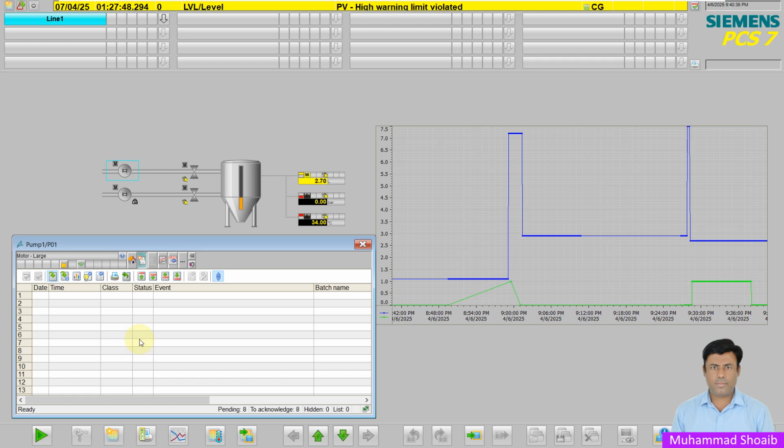The motor protection block already has some default alarms configured. That name is motor protection. It's already configured by default. But if you have some other alarms, like overheat, vibration, or MCB off or on, how can we configure those alarms and link them with this pump 1 motor?